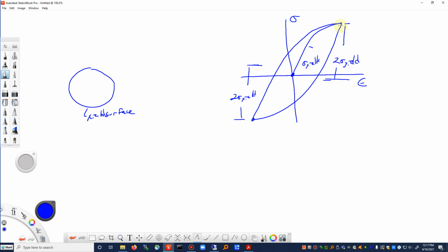So how does this relate to our multi-axial plasticity that we need to use to figure out what's going on with, say for example, our critical plane approach for fatigue analysis? Okay, well, our initial loading in uniaxial would be along our stress strain curve up to here. Where are we at with our yield surface? So with our yield surface, remember every axis represents a different stress component. I am just going to assume that as I go up this way, that represents changing this stress component. So as I go up this way, I don't have any yielding until I hit this yield surface. I'm starting at the middle of stress space. We have a material that's never been tested before. Okay, so that represents this portion of the behavior of this stress strain curve.